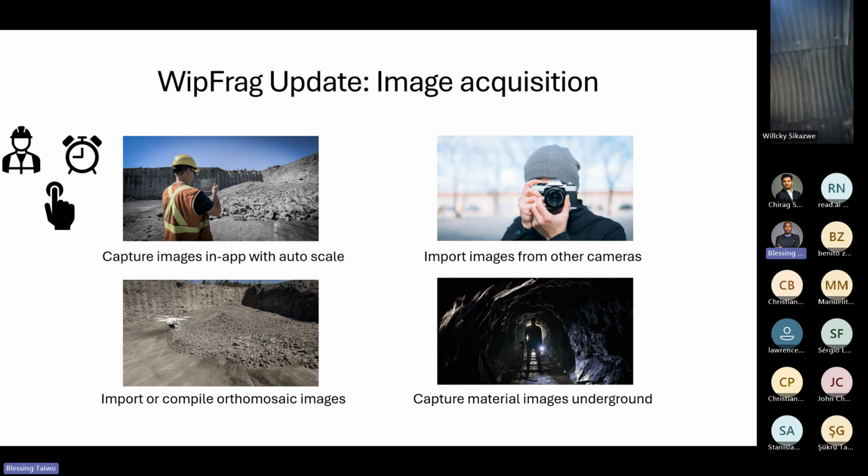The stemming zone is known to contain inert material, which will control the energy within that zone in the blast profile. So we have the stemming region, the column region of the blast, and the bottom charge. The column and the bottom charge have explosive energy to distribute horizontally within the rock, but the stemming region only has inert material which controls and confines the blast energy so it is well distributed within the rock.